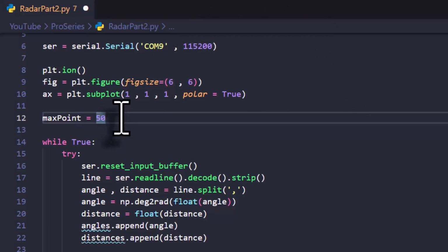filter system. There's a term called moving average. Moving average is a simple way to smooth out short-term fluctuations in a data stream. I mean, instead of using each raw sensor reading directly, you take the average of the last n readings. For example, it depends on you, 5, 10, 15, it depends on your sensor. So you take the average of the last n readings and use that average.